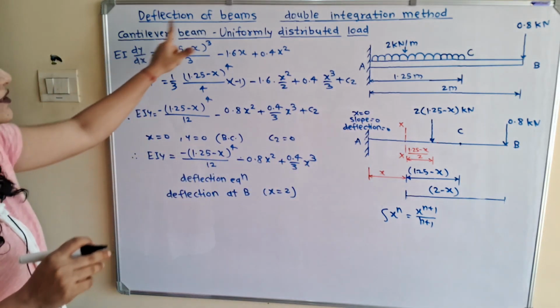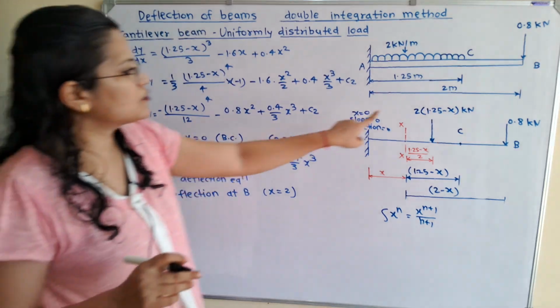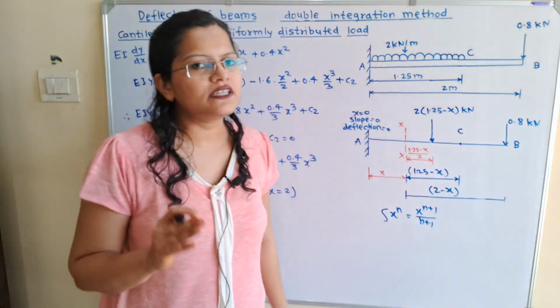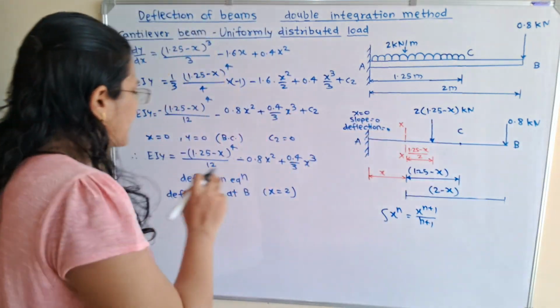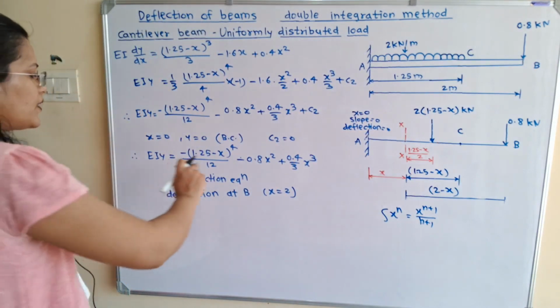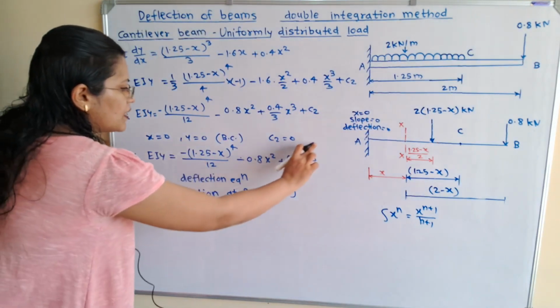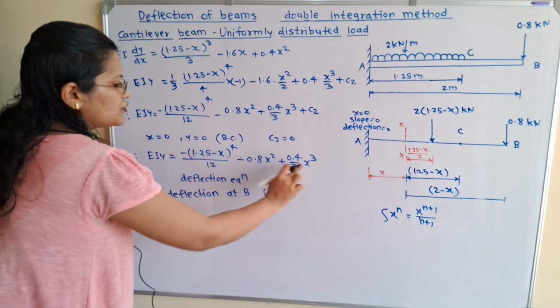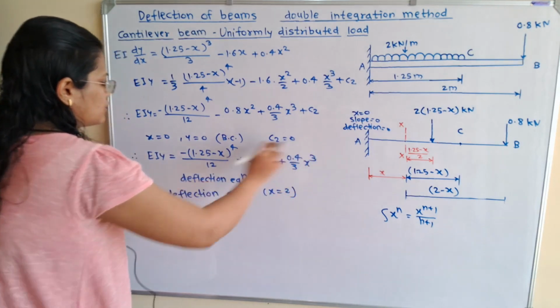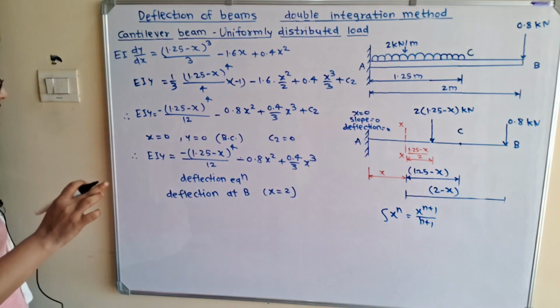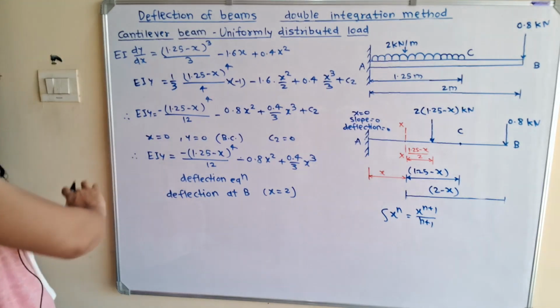Now if we observe all these calculations, here the load we have considered in kilonewton, but the standard unit is Newton. So we have to multiply this calculation on the right hand side with 10 raised to 3. So I will put the value. Deflection at B is known as YB.